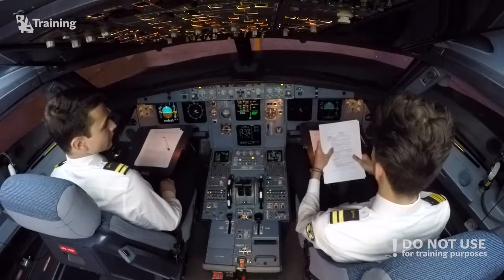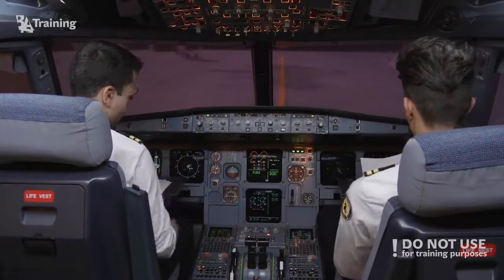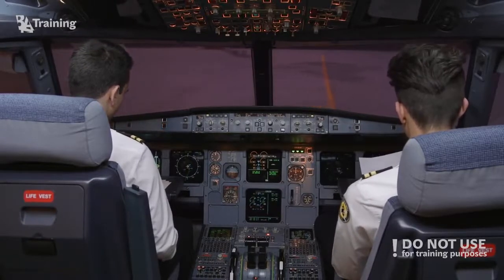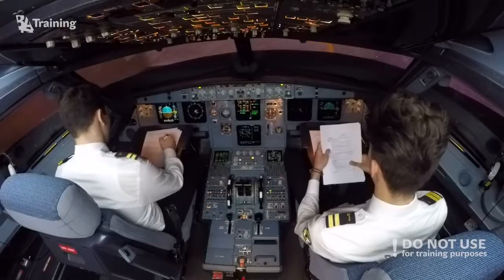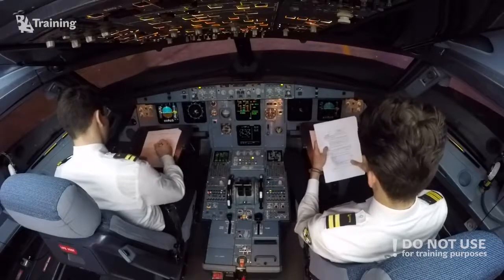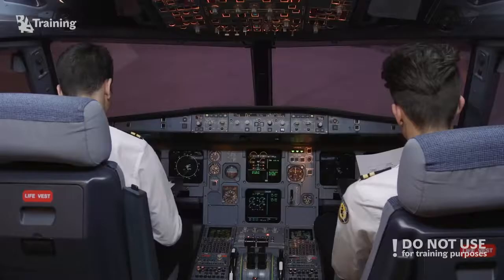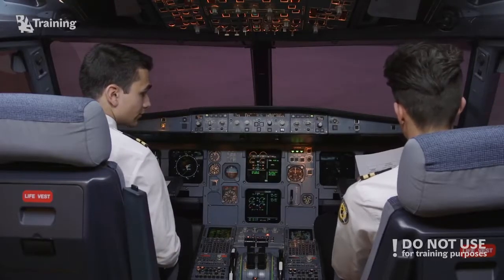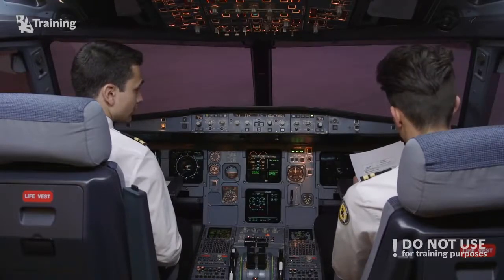In that case, the flight crew should consider a dry crank cycle of the affected engine before they perform another start attempt. Then, in the case of an ECAM alert, the pilot flying must announce ECAM actions in accordance with the ECAM management philosophy. Thrust levers idle. Caution: the engines start regardless of the thrust lever position. If the thrust levers are not set to idle, the thrust rapidly increases to the corresponding thrust lever position, causing a hazardous situation. Engine mode selector, normal, then ignition start.